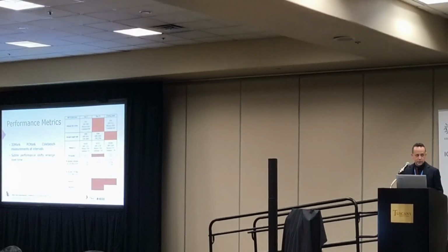Day 1 is the beginning of the experiment, so the CPU hasn't gone through accelerated aging or any thermal stressing yet. Day 21 is after 3 weeks that the CPU was operating at full load, at 100%, but without any modifications to the cooling system. So the temperature of the CPU was within the limits that the manufacturer designed it for. Just the operation was at 100%. And after the 21st day, for around 8 or 9 days, the CPU was operating again at 100%, but with its cooling system modified, so the operational temperature was 95 to 97 degrees.